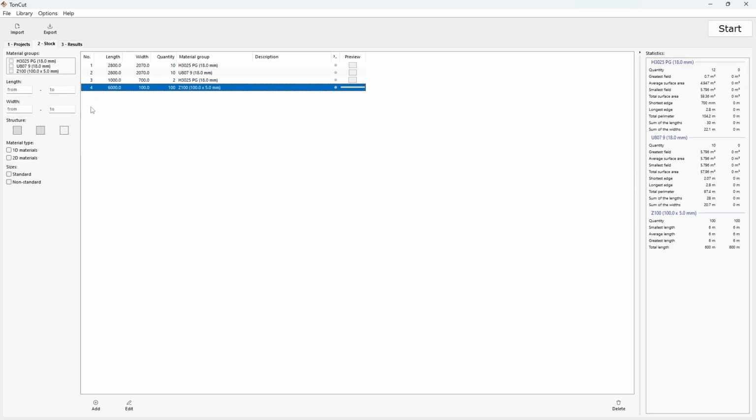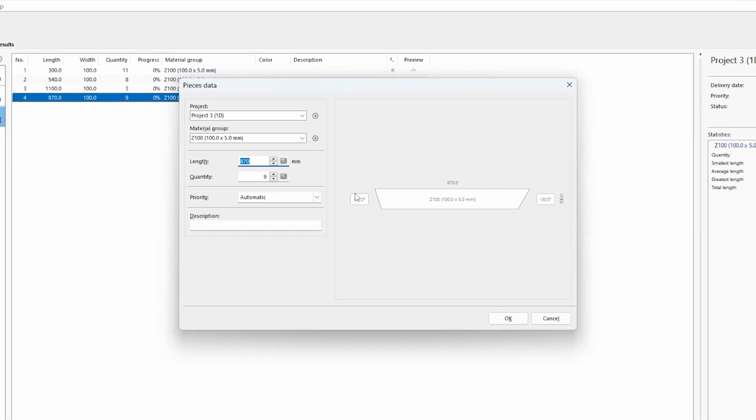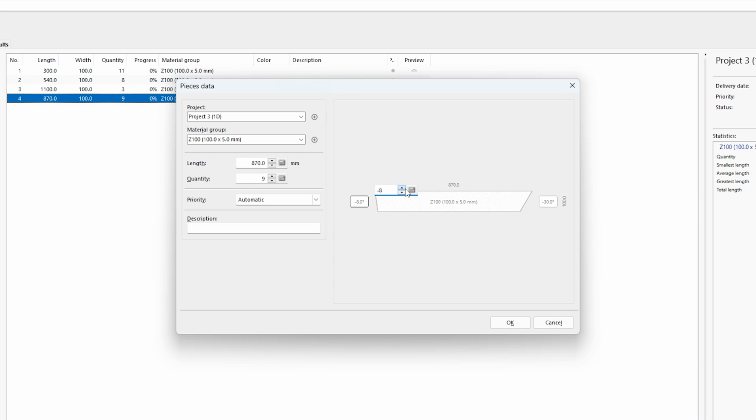As you've already seen, our pieces have some cutting angles defined. Since we're using the default miter cut settings, we can enter positive, negative, or 0-degree angles. An angle of 0 gives you a perpendicular cut. Changing the left angle to 20 degrees results in such a cut. Now let's set it back to minus 17 degrees, and now you can see how it works. Simple, isn't it? It's important to remember that when using miter cuts, the specified piece length includes the slanted ends.